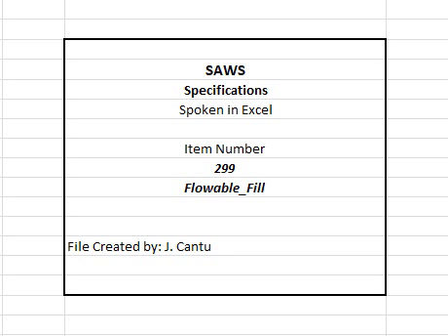299.6 Testing. Testing shall be in accordance with TXDOT Standard Laboratory Test Procedure Tex 418A. 1. Contractor to furnish all labor, equipment, tools, containers, and molds required for sampling, making, transporting, curing, removal, and disposal of test specimens. Furnish test molds meeting the requirements of TXDOT Standard Laboratory Test Procedure Tex 447A.